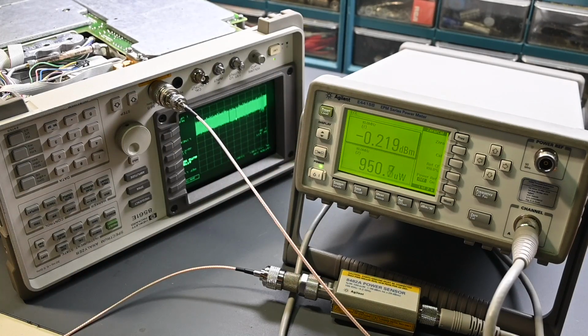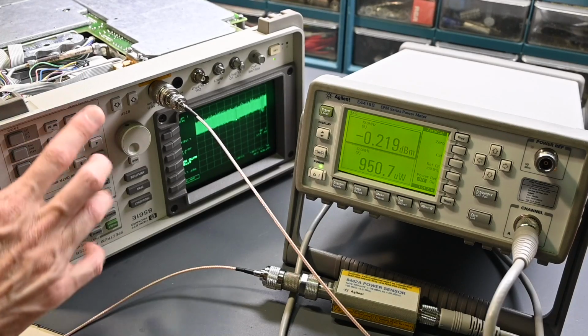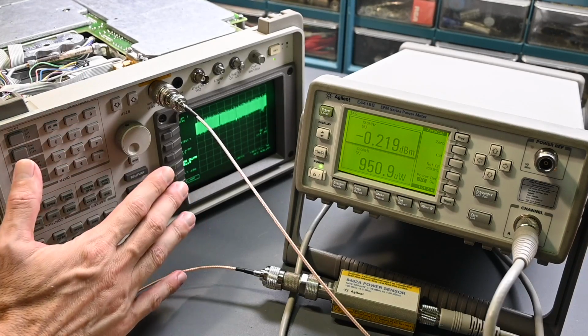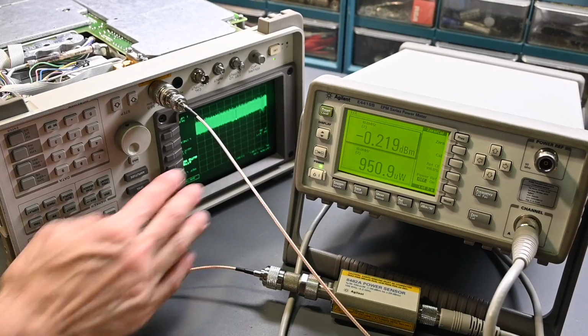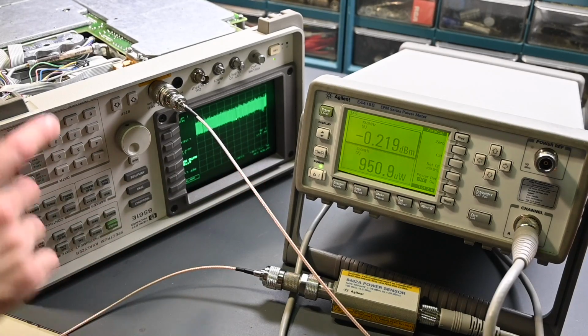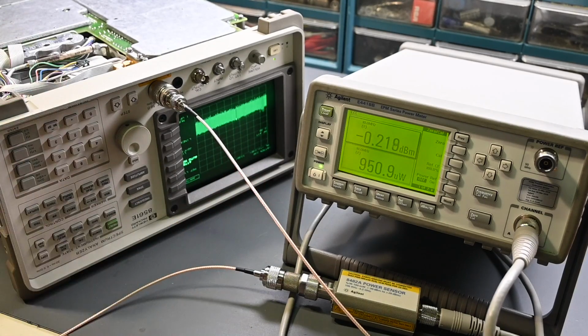So yeah, it looks like the attenuator is working okay. For the testing that I was doing initially earlier in the video, the attenuator is set to minus 10 dB and some of those values right in there, and it wasn't cooperating at all with the levels that we're seeing on the screen, but in fact the attenuator is working, so the problem must be elsewhere.